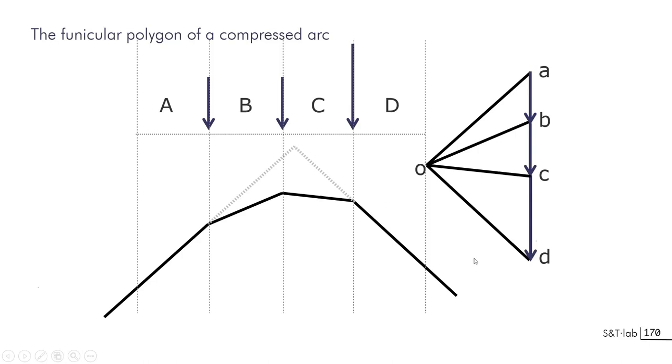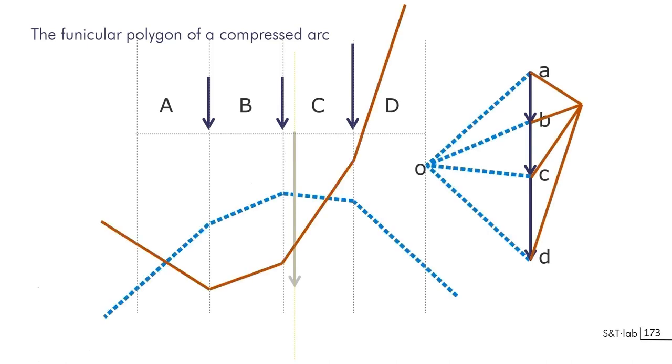So we'll have the equilibrium appearing here, and that will give you the point through which passes the line of action of the resultant forces. So that's one of the first uses. If you are doing it with another funicular polygon, for example, in traction, you will have the same kind of result by lengthening the extreme rays of the funicular polygon.